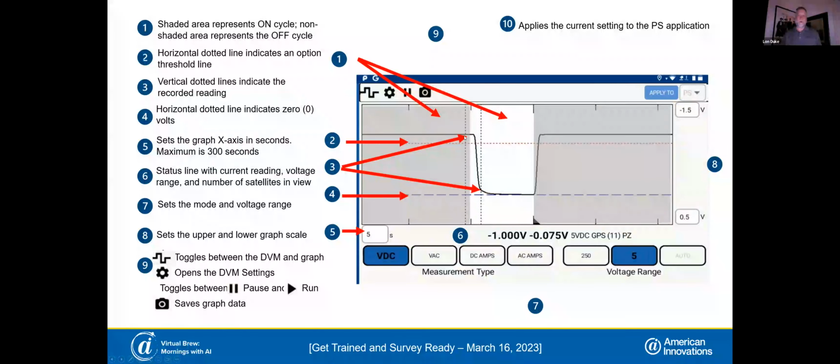This is actually a 4 on and 1 off, if we saw the full waveform, so you can adjust that out. Usually, I like to adjust it out to where I'll see 2 waveforms in a screen. That way, I know if anything is moving, I can see it. And it's consistent with each waveform.